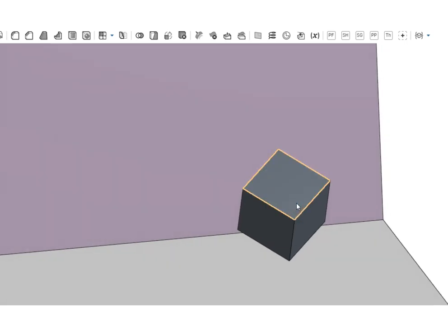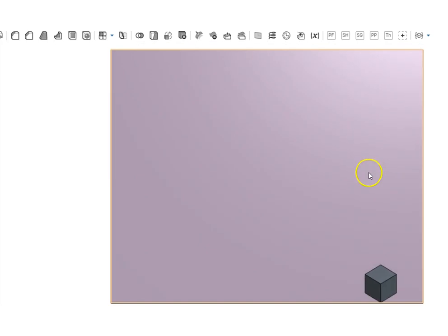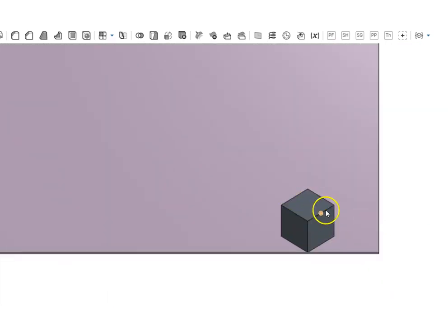So basically, looking at the steps, first of all we rotated the cube by 45 degrees, so that in the top view you get the corner. The next step, we rotated with respect to the horizontal plane, so that the body diagonal becomes parallel to the horizontal plane and parallel to the xy line. And then again we rotated the cube 90 degrees with respect to the vertical plane, so that the body diagonal became perpendicular to the vertical plane. So this is the three-step process by which we have achieved this. So let us now see this in practice, how to actually construct this projection.